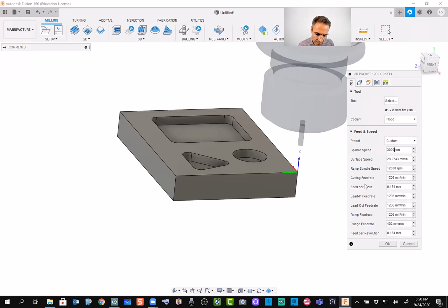You may say that my feed rate, I don't want it to be that fast, all right? Instead of 12,000, I set it to maybe 200. It's going to be very slow, but this is what we decide to do, okay? And the rest, we just leave as is. Two numbers then, the spindle speed and the feed rate, all right? We have the depth of cut, so we can look up the stability law in future, but for this practice, you can again play with these things. So we select the tool, we select the feed and so on, and then the geometry.